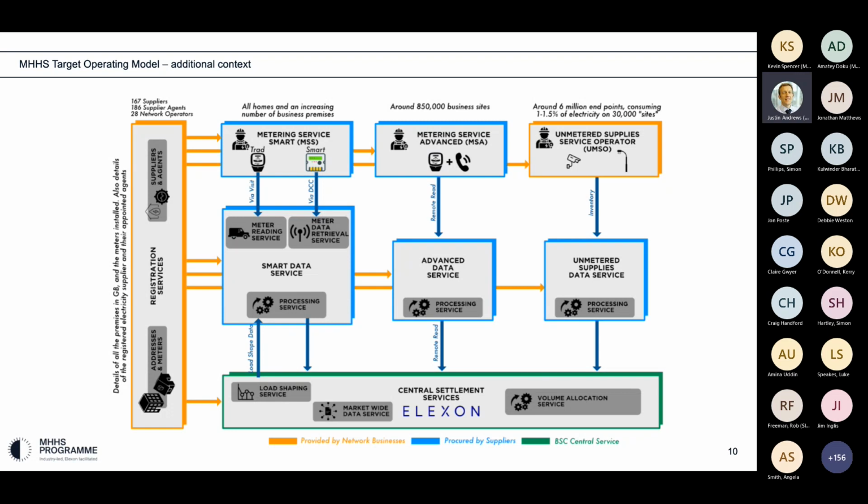So is another way of answering that, you've got a new site, you haven't got any data. I presume the smart data set, we do have something at the moment called the EAC, the Estimate of Annual Consumption, and there is a proposal within the design documentation to replace that under market-wide half-hourly settlement, and there are various options on that. And I presume then in that case, Kevin, that sort of EAC could be used, which would then be used with the load shaping data to estimate and put in half-hourly data for that particular meter.